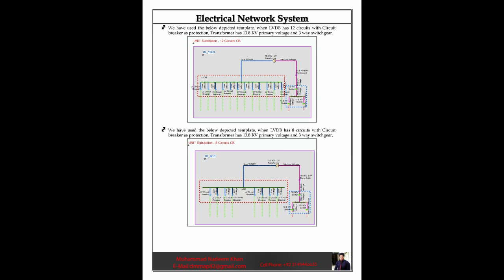We have used the below depicted template when LVDB has 12 circuits with circuit breaker as protection, transformer has 13.8 kV primary voltage and 3-way switchgear. We have used the below depicted template when LVDB has 8 circuits with circuit breaker as protection, transformer has 13.8 kV primary voltage and 3-way switchgear.